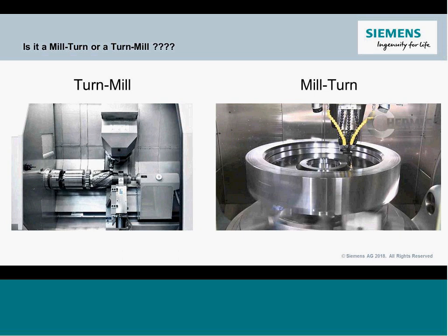type that was leveraging milling, and that's really a lathe that we're incorporating milling functionality into. And in the last few years, motor technology has gotten to a point, specifically leveraging torque motors, where you can take a spindle of a large 5-axis milling machine and get it to run at RPMs where you could actually turn. So, proficient in both sides of the technology, we started changing the terminology a little bit.